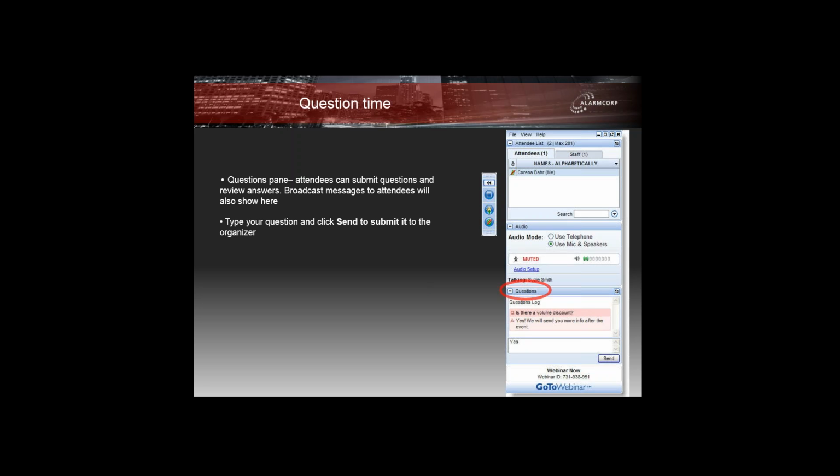Ultimately, both detectors are the same in the way that they work. It really is more a marketing exercise rather than a technical limitation as to why the GM 760 isn't on the approved list. That ultimately doesn't affect installers or the end user at all. The GM 730 is considerably cheaper than the GM 760, and really its only downfall is it's got a 1 meter less radius than the GM 760.